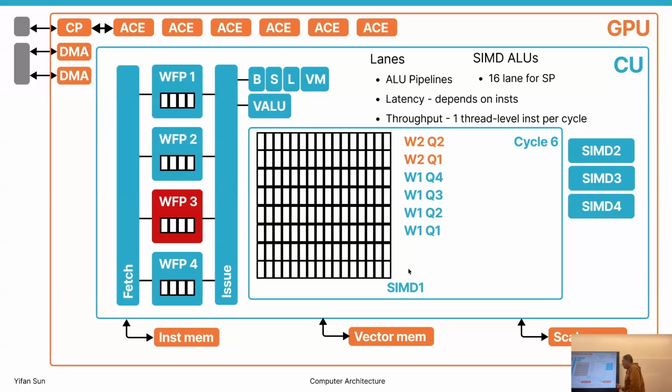In theory, especially for compute-oriented GPUs, the design is optimized for throughput, not for latency. So we can allow a longer time to access, say, memory. GPUs do require longer time to access memory compared to CPUs. But because there are so many other threads waiting, a GPU can deliver much higher throughput than CPUs.